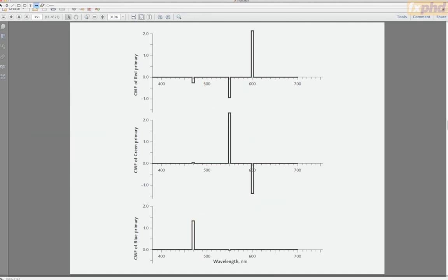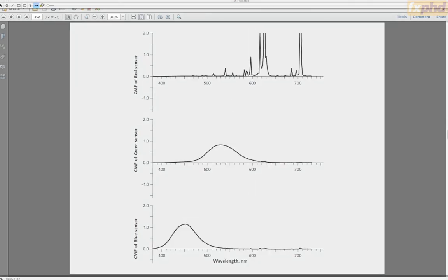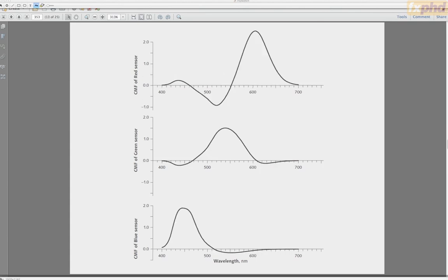So flip that idea around and ask, if I can't display those directly, what can I display? Well, this is the spectral power distribution of a Sony Trinitron CRT. What would I use to sense 3 signals to directly drive that CRT? This is very close to Rec. 709. The answer for what you use at the camera is this.